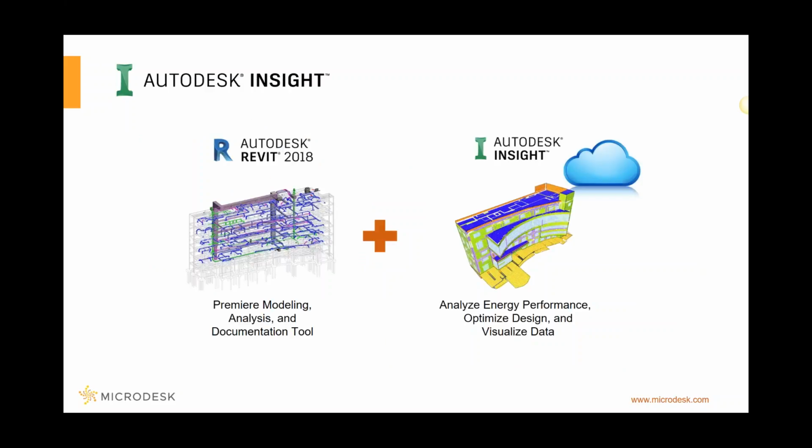Now, Revit includes direct access to building performance analysis using Autodesk Insight. With the push of a button, you can send your Revit model to the cloud for analysis, allowing for rapid iteration using Autodesk's extensive cloud processing power. Results are quickly returned in a visual, easy-to-read format, making it easy to identify opportunities to improve your design. You can even see how the data was calculated.